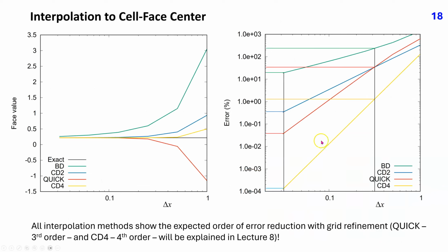First, we check the order of interpolation alone. The left figure shows how the value at the center of the phase changes as the distance of neighbor cell centers changes through grid refinement. This is checked by refining the grid in x direction alone, because when the grid is refined in both directions, the location of the cell phase center moves to another location, but we need it to stay fixed to check the convergence with grid refinement.